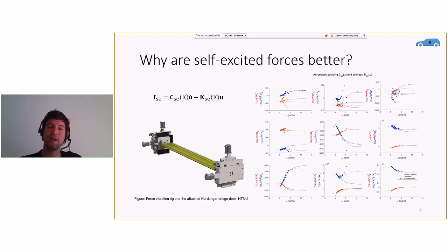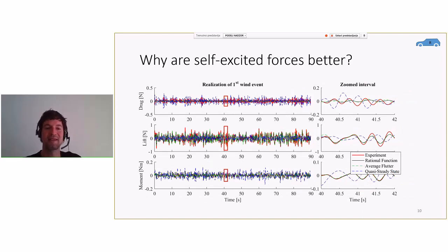And what we explore through research is a new way of formulating the self-excited forces, and we are now allowing the use of polynomials as well, because we're taking a more general approach. So that will be, of course, a big benefit, to have this simple way of fitting the data. And these are actually measurements performed in the wind tunnel. Yes. So this is how we get it, and this is one of the tests that has also been conducted. Based on the data we have up there, we can fit our numerical models.